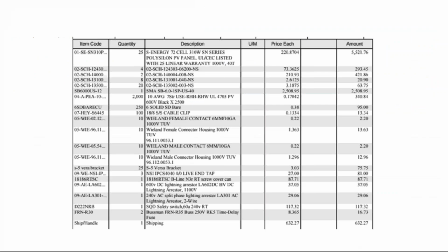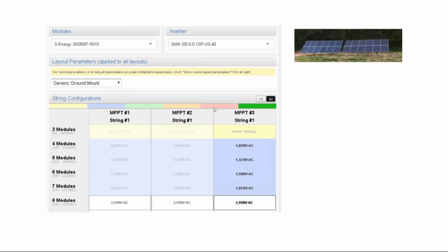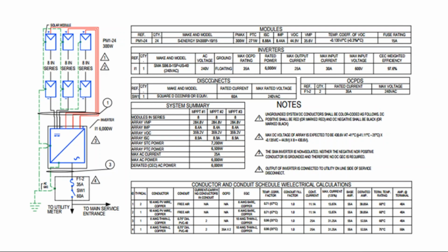And so what I'll end up doing first is just going into my traditional solar design software and designing the wire diagram based in my software, but then ultimately off-grid design, you're exporting it into AutoCAD or DraftSite, which is kind of like a free AutoCAD, and then finishing it out.